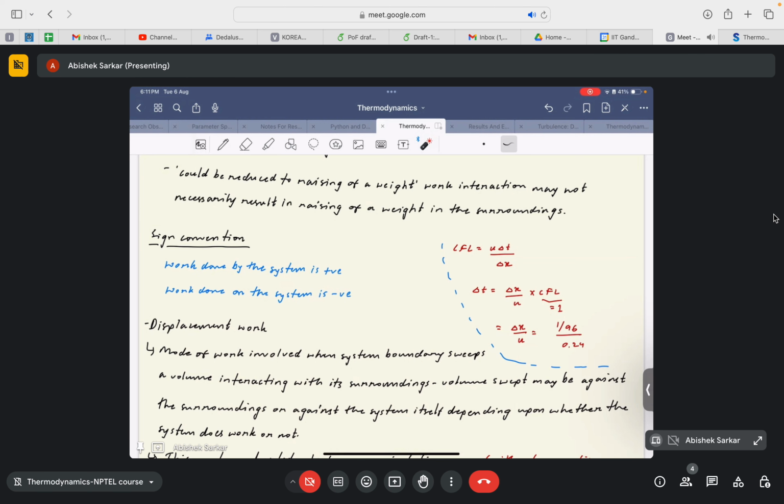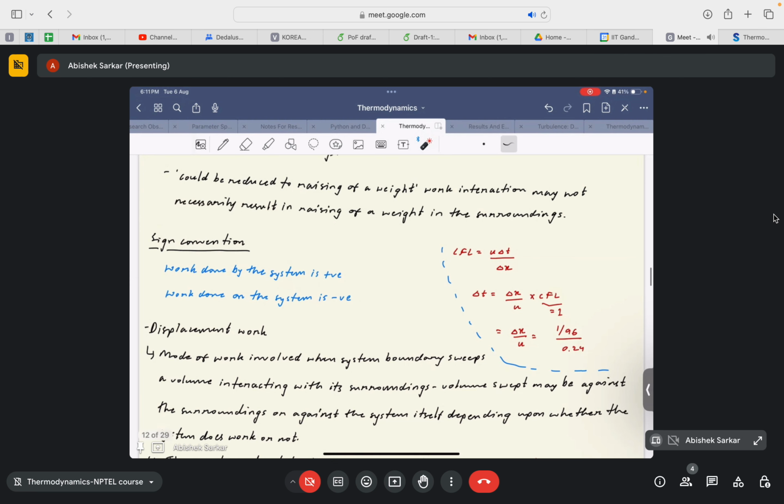So this kind of sign convention is usually used. Most of the standard textbooks follow this sign convention, but there might be some authors or researchers that may use the opposite one. That's also correct. It's just their way of assigning a particular sign to the heat and work interactions. But this is the most standard way, and I will suggest you follow the similar convention, because this would become quite handy if you are aware of the standard sign convention that is usually used.